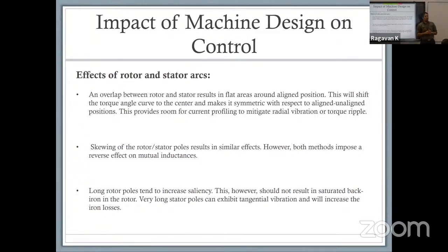It'll have a little bit of a back and forth swaying motion at the rotor. It will twang to a stop, so to speak. At the same time, you are trying to make sure you also have the air gap right when you have the right arc length. You're trying to use that also to control the amount of torque ripple.